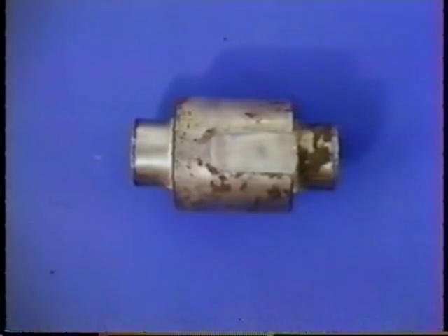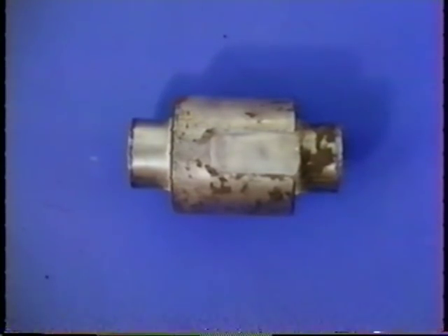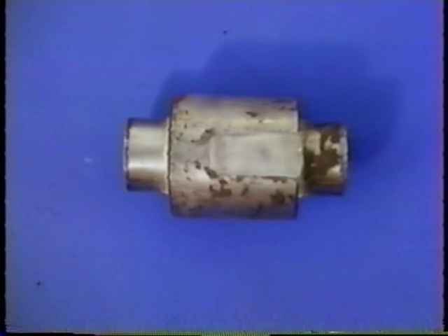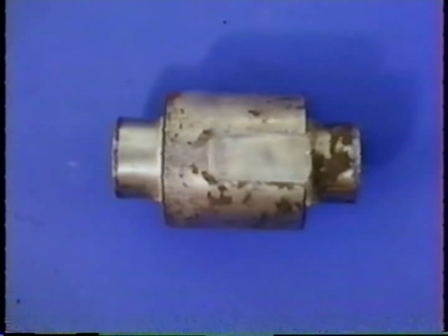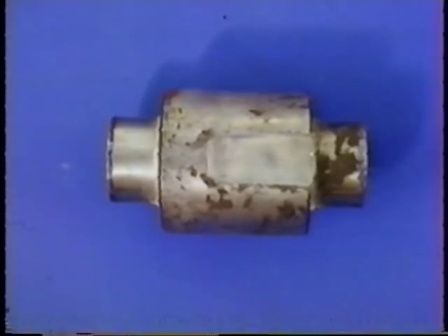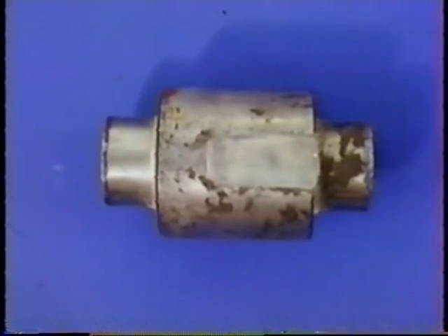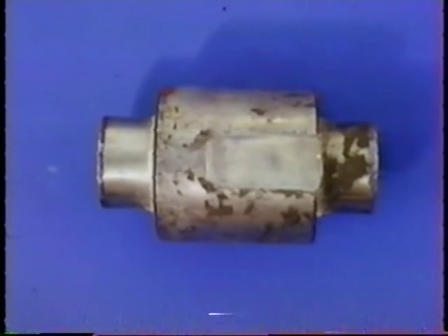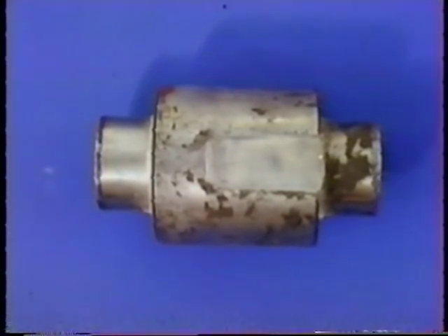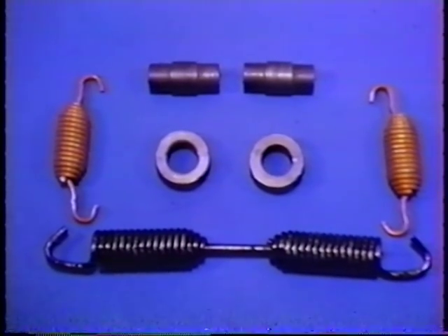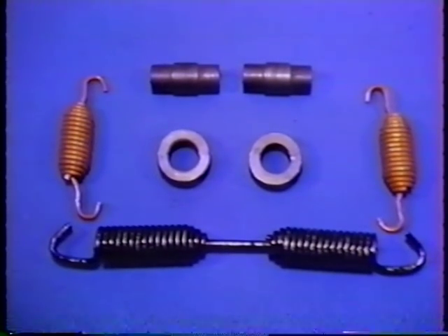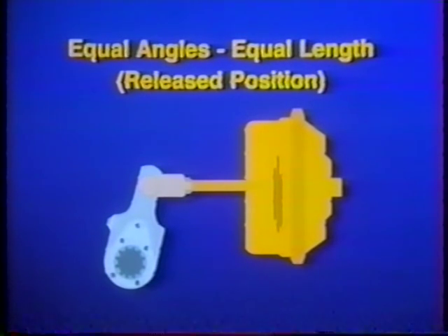Worn parts are another crucial factor in mechanical brake balance. Wear on a single part may seem insignificant, but a combination of worn anchor pins, loose cam bushings, tapered rollers, and stretched springs can add up to cause excess slack in the system. It's far more practical and cost-effective to replace each part every brake job. Proper linkage adjustment is just as important to mechanical balance.